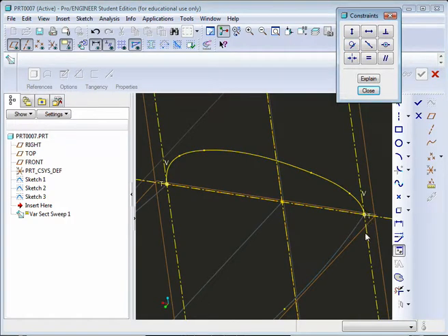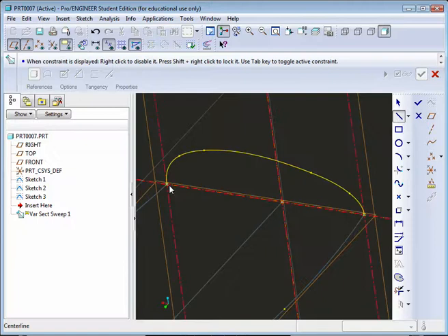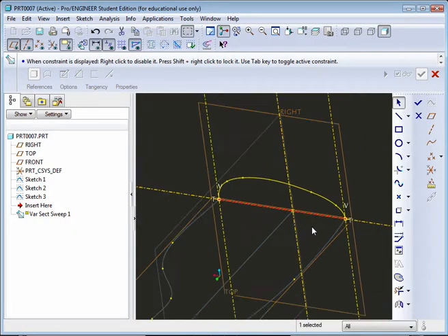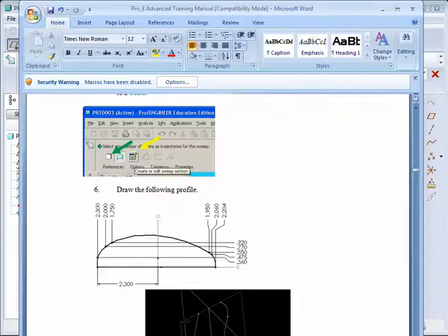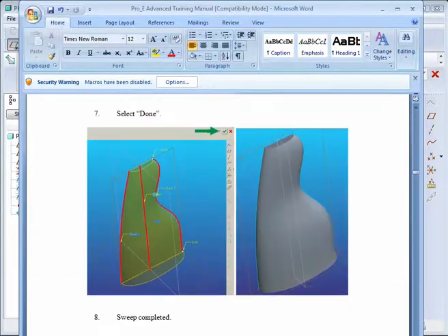And in this case, it will be a little bit smoother when we look at the side profiles of the bottle. And then take the line tool and close it off at the base. So from here to here, you want a solid line. Okay. And now we just go ahead and we hit done.